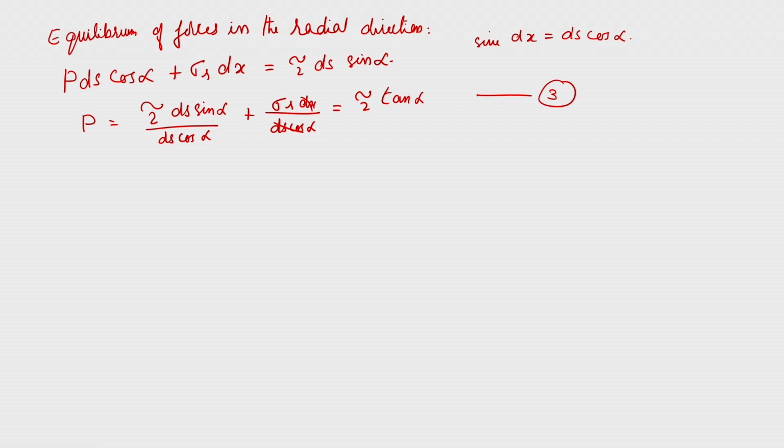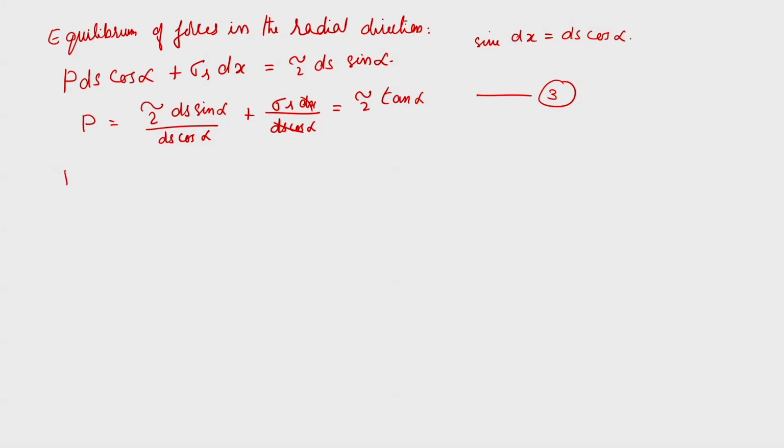Now, we were just considering the case of a cylindrical billet, and the extruded piece is also cylindrical in shape. This is the simplest case we were considering. Because this is axisymmetric, the principal stresses can be assumed as sigma 1 is equal to sigma x, sigma 2 is equal to sigma 3, that is equal to sigma r. Sigma 2 is equal to sigma 3 is the radial stress which is coming.